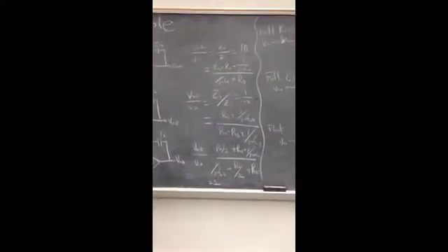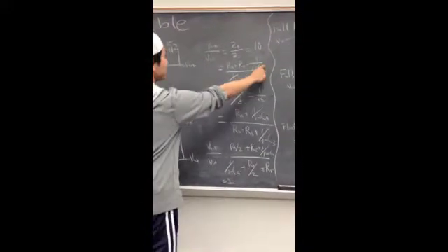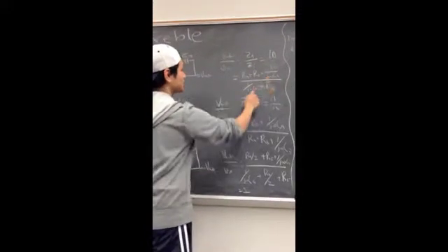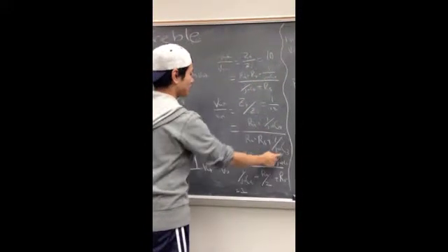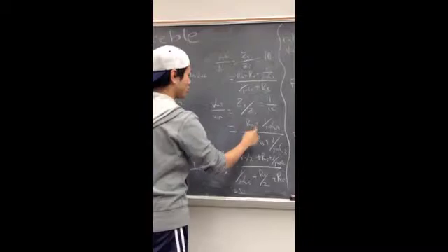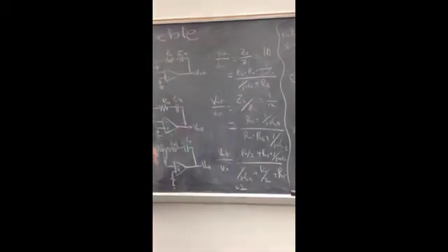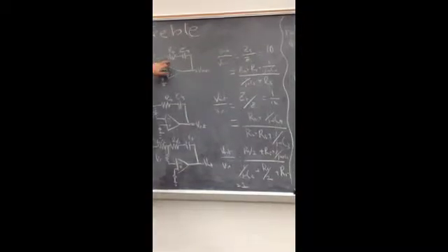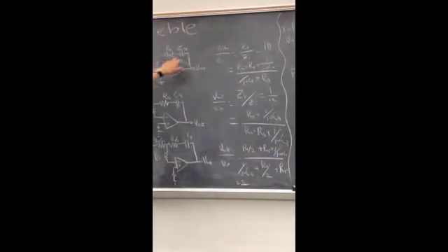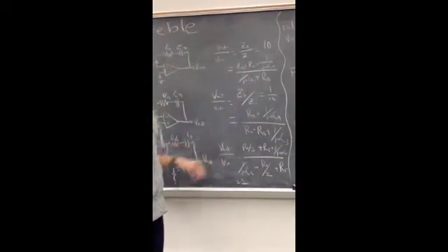And similarly, for full boost and full cut, we needed to pick values that gave us 10 or 1/10. So basically, if you look at these, at high frequencies, these circuits are shorted out, and we only have R5 and R4 contributing to the circuit. So R4, the maximum value of the potentiometer, needed to be around 9 to 10 times larger than the